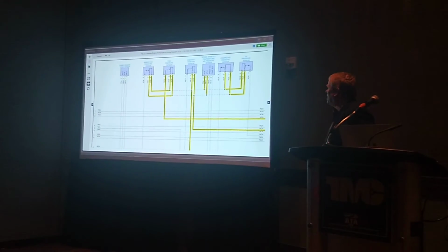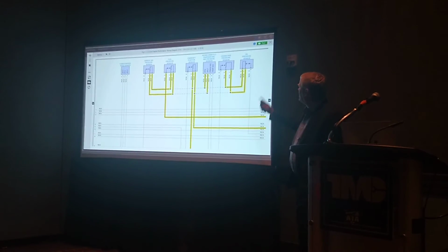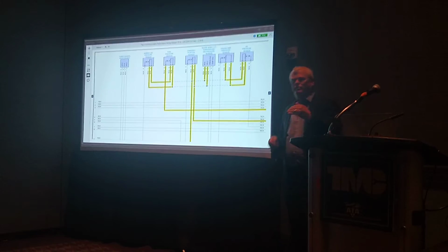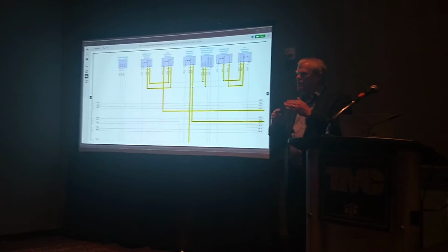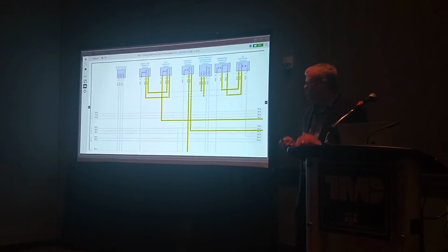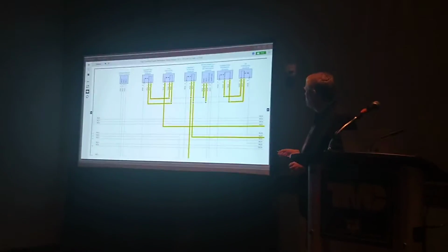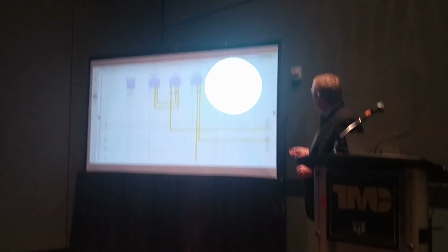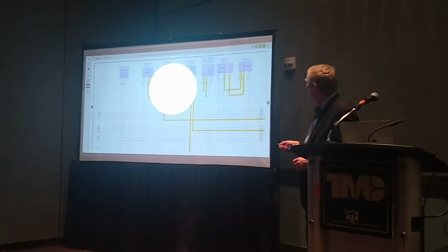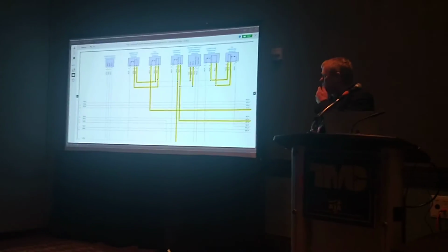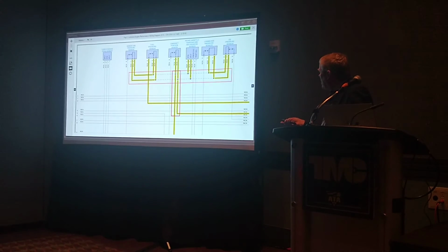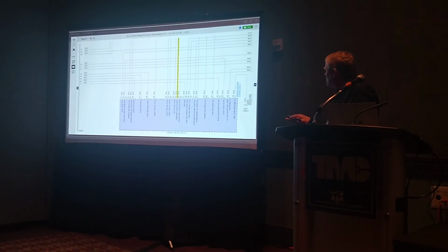And, you know, kind of diving a little bit deep, but all these sensors, I was interested in this fuel pressure sensor right here, and it's a variable feedback potentiometer type sensor. You've got a voltage, a ground, and then a feedback loop. And if you notice, it shares that feedback loop across this circuit with the oil pressure sensor, the crank pressure sensor, the cam position sensor, a lot of these sensors. So if I actually had a common problem, now I could quickly scroll down and find out where that terminates.